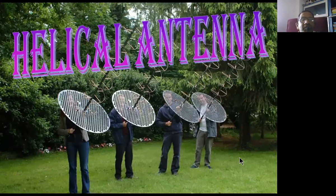And we are continuing with our discussion on the loop antennas. So, in that, we have another loop antenna called the helical antenna. In the previous class, we discussed the single loop antennas, such as circular loop antennas and rectangular loop antennas, and today's class will discuss the helical antennas. Helical antennas also come under the loop antennas.